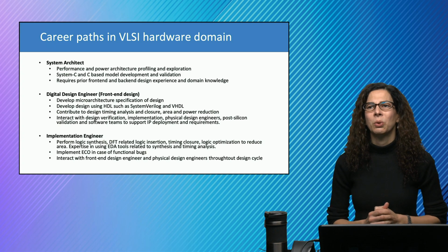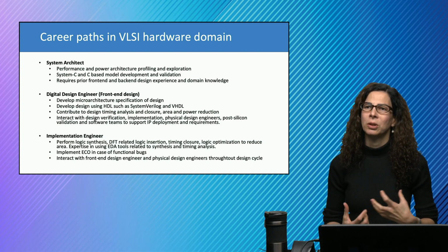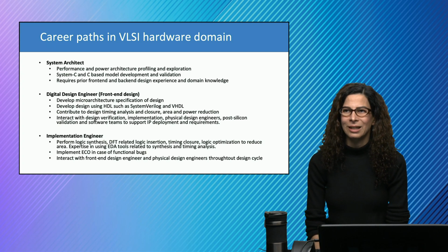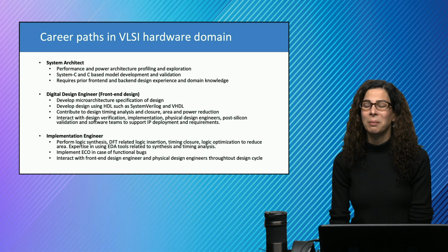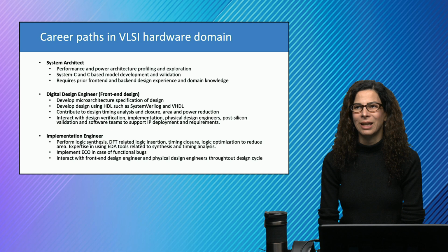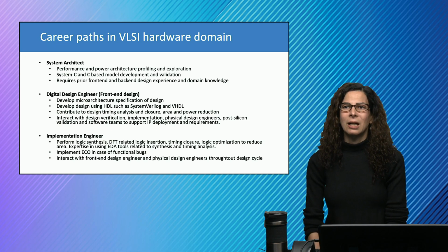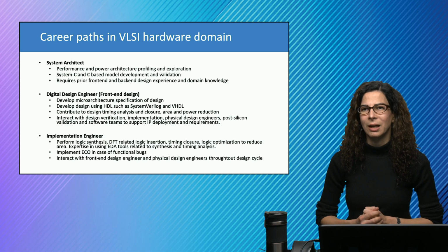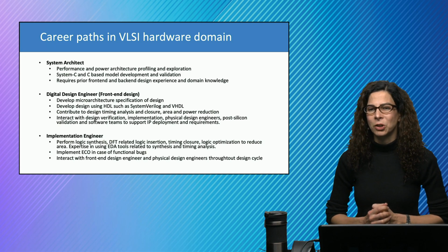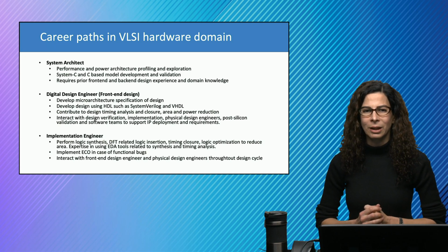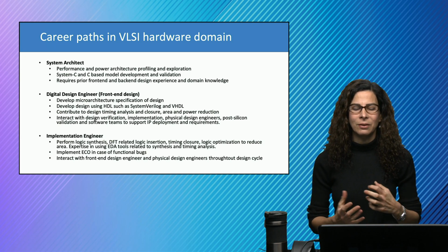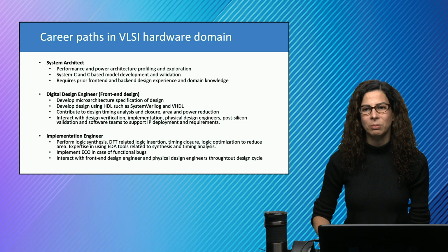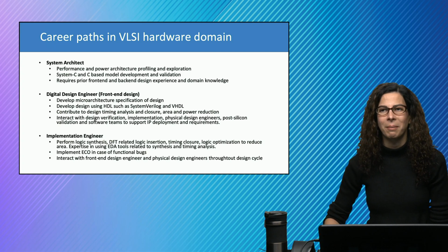We need to go through this multiple times to make sure that we get timing closure. We can optimize logic, and a big number of iterations has to be done before we reach closure with a complex design. But then functional bugs have to be taken into account, and both the front end and back end have to interact with each other to make sure that the specifications are met.